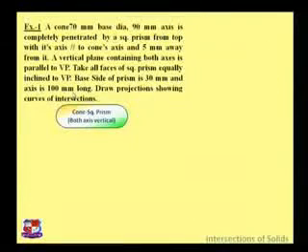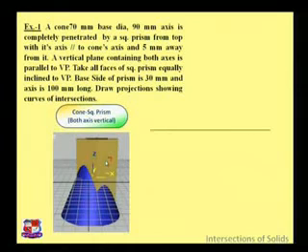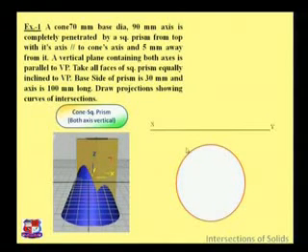So first we draw this problem. This is the view of the given condition, a cone and a square prism. First we draw the XY line, which represents the intersection of HP and VP. Then after naming the XY line, draw a circle of diameter 70 mm. This is the top view of the given cone. A cone is resting on its circular face and its top view would be a circle as shown over here.